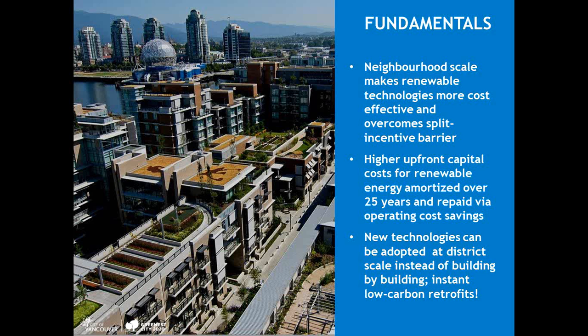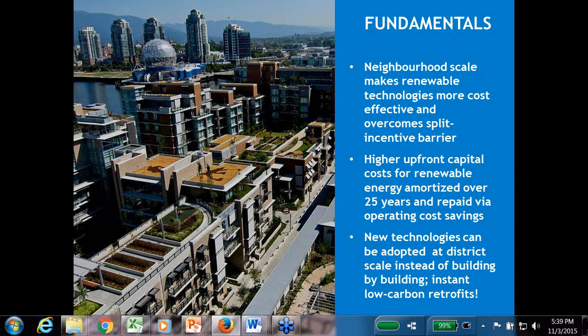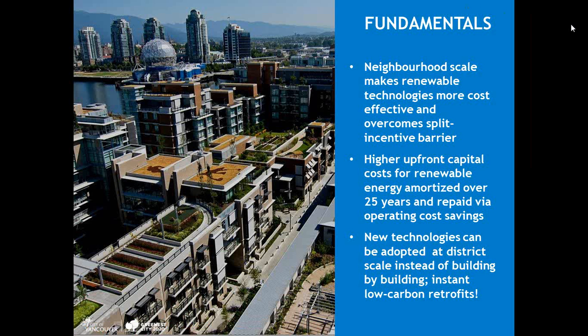The other piece that led us into this path was that it is adaptable. Currently, the system I'm speaking of uses sewer waste heat pumps, but new technologies can be added into different systems, and those systems can be integrated into a grid. Over time, if a better, more cost-effective technology becomes available, instead of trying to retrofit 100 buildings in the downtown core, you can retrofit a whole district energy system to the new technology and effectively reduce the emissions from a large number of buildings.